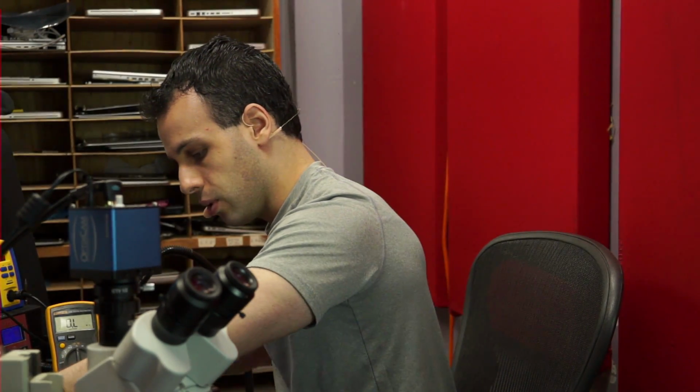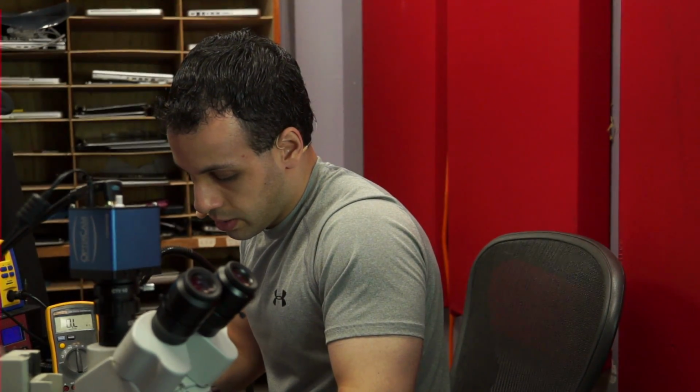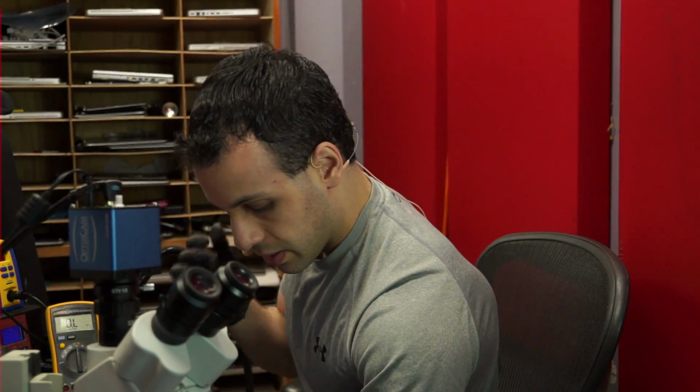We're going to take a little bit of a look at what it looks like on the other side. Now, do keep in mind that in order for the backlight circuit to work, it does have to detect a screen, as I said before, which means I'm going to have to find some convoluted way where we plug the screen in and then do our measurements on the other side of the board. So I'm going to plug in the screen over here. And I'm not going to attach the hard drive because I don't want the machine to go to sleep. I don't want the screen to turn off. If there is no drive plugged in, there is no operating system, it's going to stay on in EFI mode and never get to a point where it's going to turn the screen off, which is a good thing here.